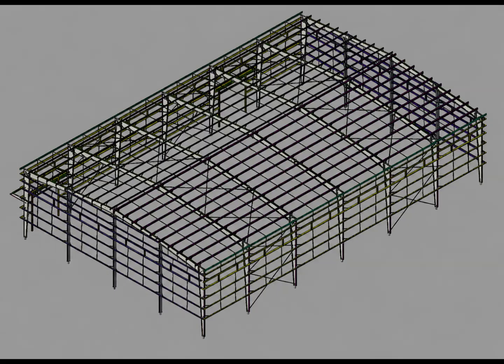However, one important rule should always be remembered. A 3D model should not replace the approved engineering drawings. The drawings and project details remain the basis for the actual member sizes, dimensions, connection requirements, and design information. The 3D model is extremely useful for visualization, coordination, detailing, and understanding the spatial arrangement. But the actual project information must always be checked against the approved drawings and specifications.